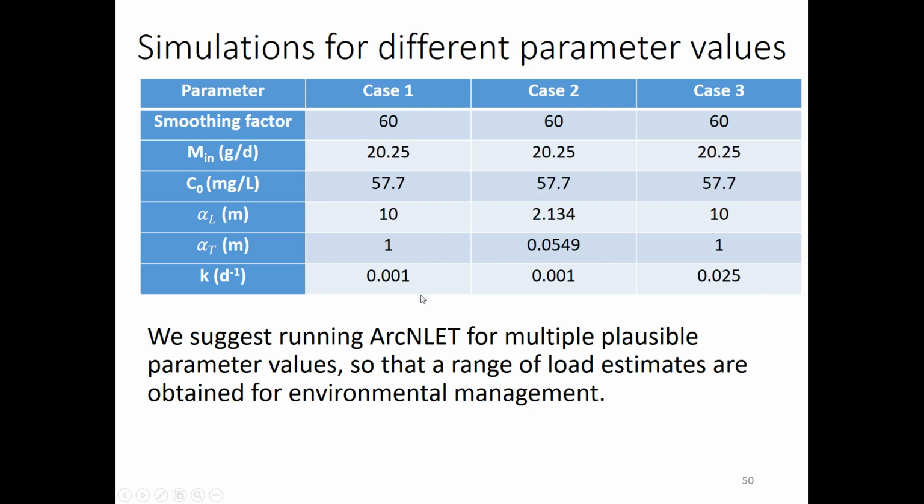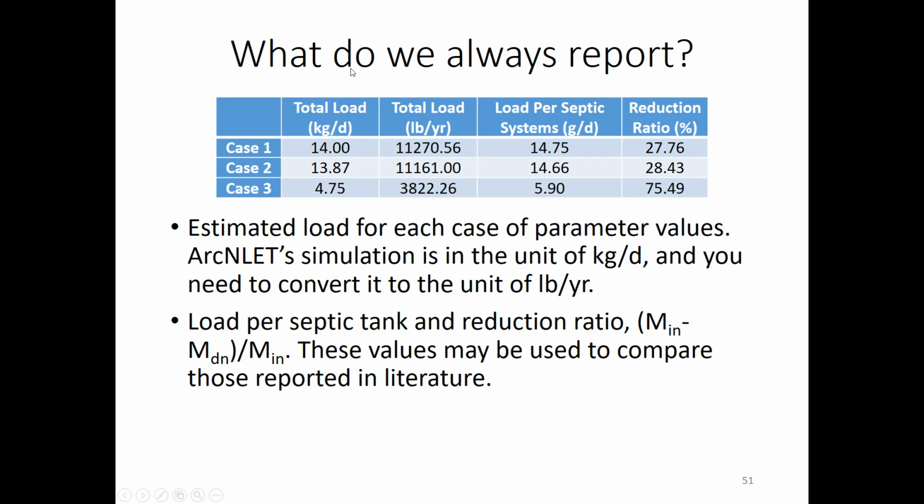When you run ArcNLET for your case, you may pick the numbers that you feel comfortable with and run ArcNLET for different cases with different combinations of parameters. Then you have a range of load estimates that can be useful for your environmental management. So after you run the different cases, for each case, what do you need to report?